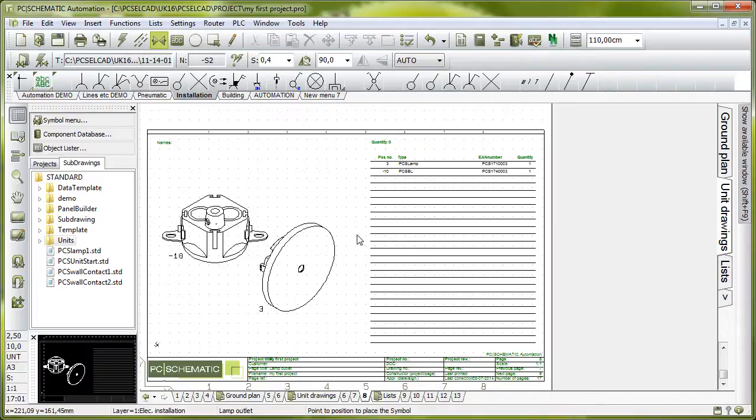Units are sort of a sub-parts list. You could consider the same thing, and you can make it in this way, or you can create exactly the same thing or equivalent to it in the database. But right here I'll show you the unit drawings and how to use them. In one of the other videos I'll show you how to make it yourself.